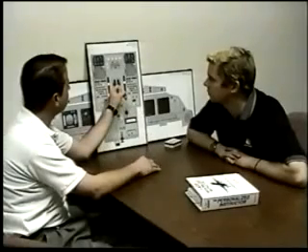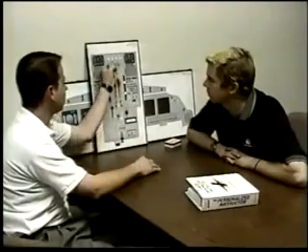That would be the flaps in the takeoff range, the pitch trim in the takeoff range, the spoilers are armed, and the rudder trim on the later A320s and on all the 319s. We also check for the side stick fault by takeover, the doors not being closed, and the brake temps. Okay. What are some items that advancing the thrust levers for takeoff checks, but the takeoff config does not? That would be the parking brake being set, because we want to be able to do the configuration test with the parking brake set, and the flex temp not set.